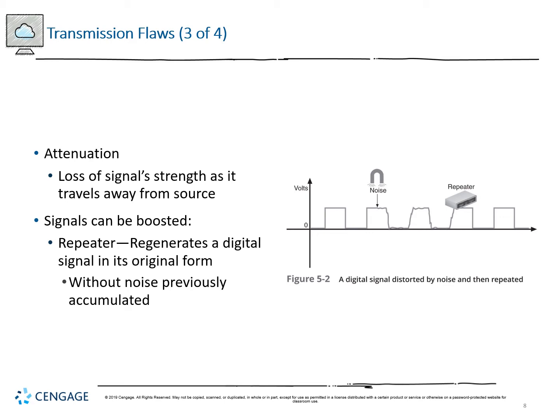The distortion that can be created by losing that signal strength over time, meaning that it's more susceptible to noise, can then become much more pronounced. If we look at the graphic on the right-hand side, figure 5.2, just after we pass the second peak, you can see that the differential between the original wave and the new wave is pretty pronounced. We see that it becomes much more trapezoidal than square. We see a lot more variation along the edges of the signal.